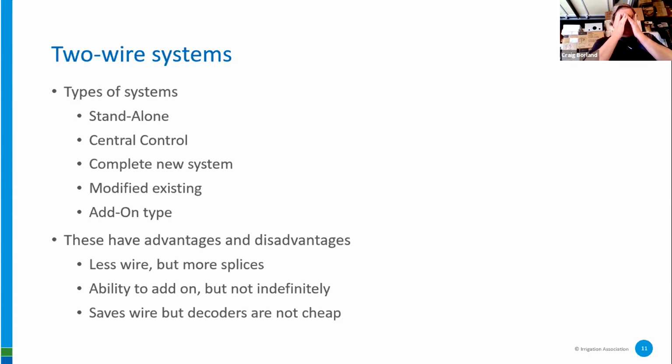very important to somehow, some way, and it's another course that we teach, validate the integrity of the existing wire to be good. Because if there's any deficiencies on that wire, weakness in the insulation, cracked insulation, leaking to earth ground because some subterranean mammal has nibbled on the insulation. I mean, gophers, ground squirrels, creatures that burrow, they can get after wire, because what's the difference between a wire and a tree root to a subterranean mammal? There isn't any. They'll chew through either one of them with no damage to themselves. They'll go right through it.